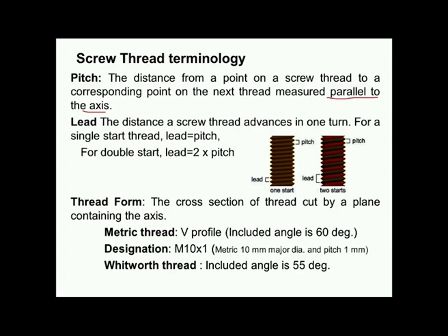Now, what is lead? It is the distance a screw thread advances in one turn. When we rotate the screw thread by one turn, the distance moved, the axial movement of the thread, is called lead. For a single start, lead is equal to pitch, whereas in the case of two start screw thread, lead is equal to twice the pitch.